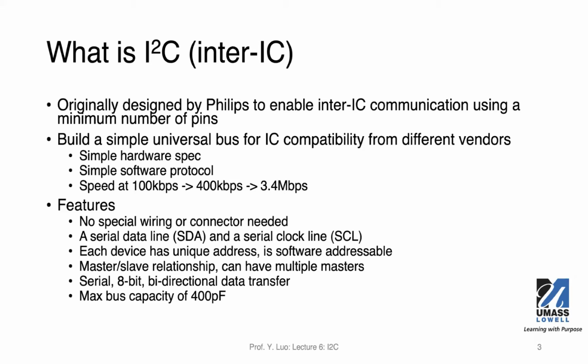I2C protocol has a few great features. There are no special wiring or connectors needed. You have 2 lines. One is called serial data, denoted as SDA. The other line is serial clock, denoted as SCL. Each device on this I2C bus has its own unique address, and it's software addressable. So you can use your program to select which device you want to talk to.